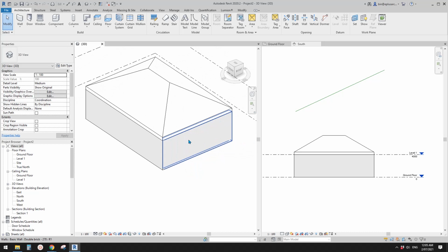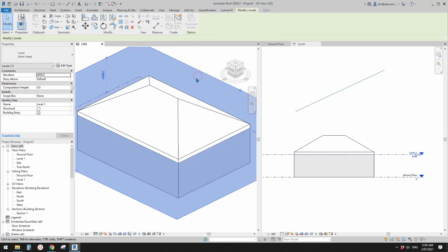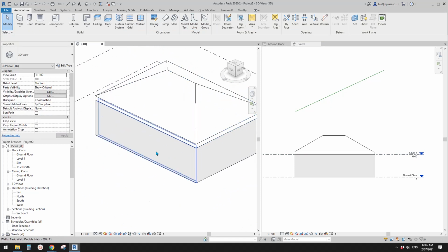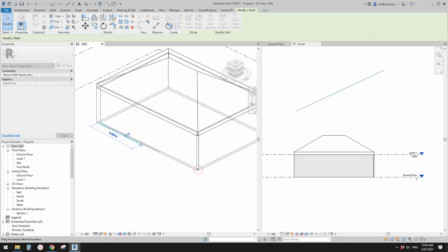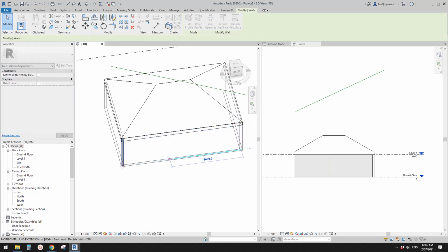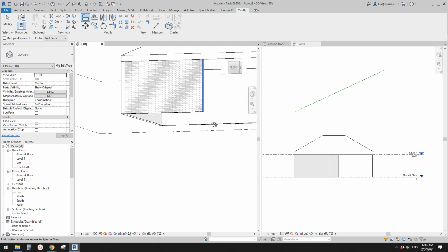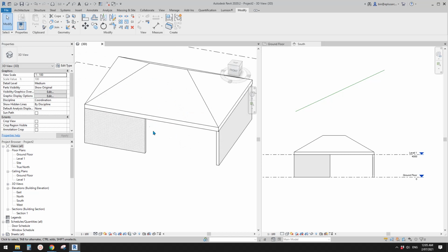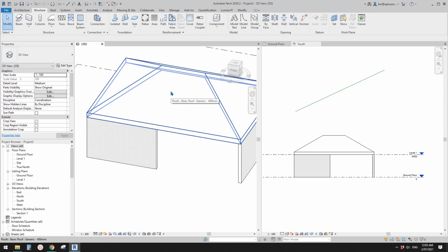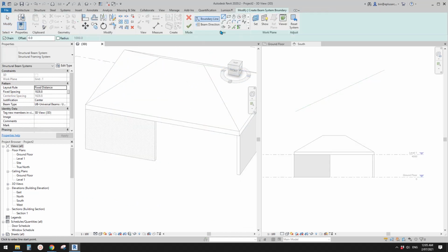Let me just do another example of when I think I will use edit work plane, then pick new. So sometimes, for example, I draw... let me just drag this back. Maybe I'll just drag this back as well. Okay, so now I'll align the opening. So I'll create two openings with the same width, and I'm going to draw a beam system. I use beam system for some patterns.